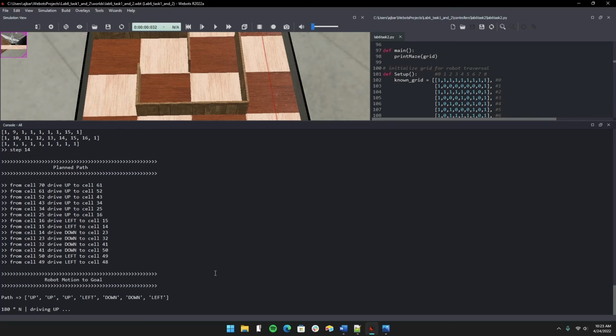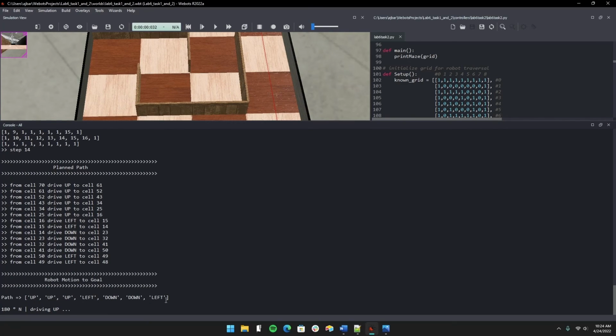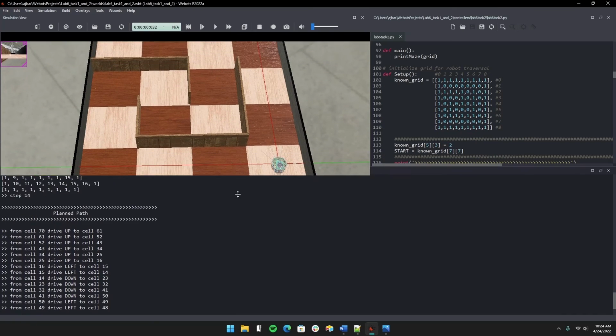The actual robot steps take every other instruction there as a motion, because it's only a 4x4 grid that we're actually running through, where my matrix is 9x9. So where the plan says to go up 6 times in a row here, we're really only moving the robot up 3 squares from where I'm at, so 1, 2, 3. And here is that plan that's printed out in steps, cut down for the robot to understand. So this path print here that's highlighted is the actual path that the robot gets sent to execute. I'll run the whole deal now so you can see how it all plays out.